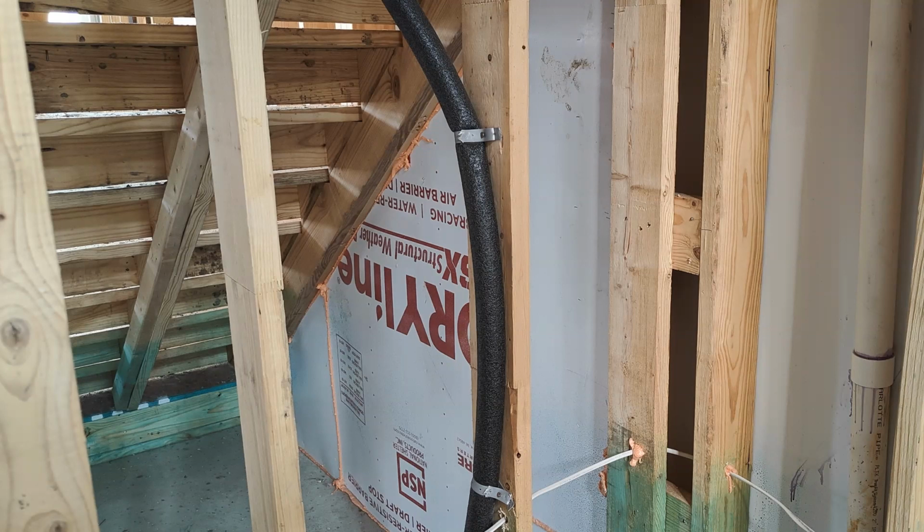is, think of the house. If this was a square box and it was a house with nothing else in it, just four square walls, you have all the exterior walls insulated and all of them will have an interior and exterior air barrier. The exterior is T-ply or OSB or ZIP board. The interior is either sheetrock or some other type of hardy board or paneling or something of that sort